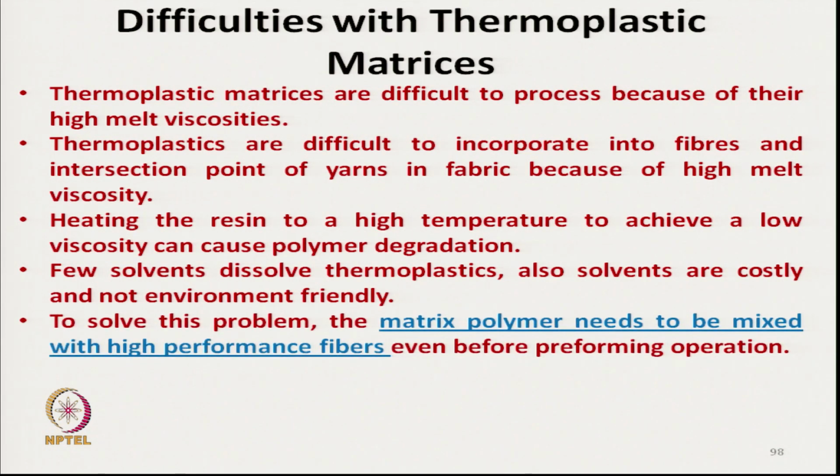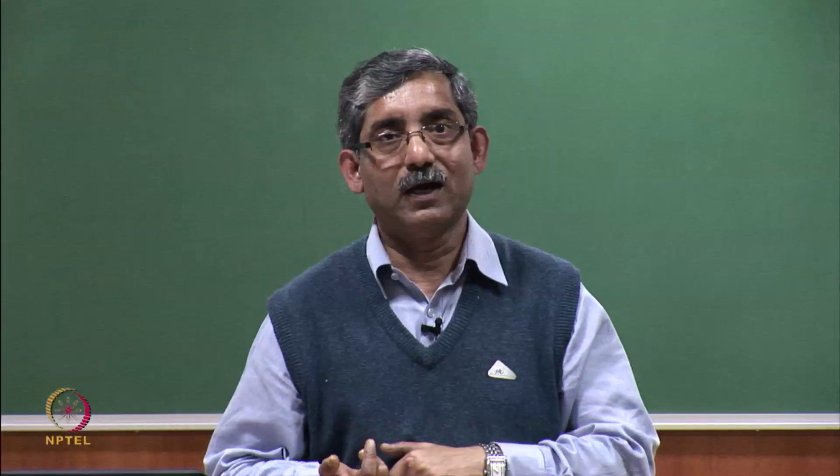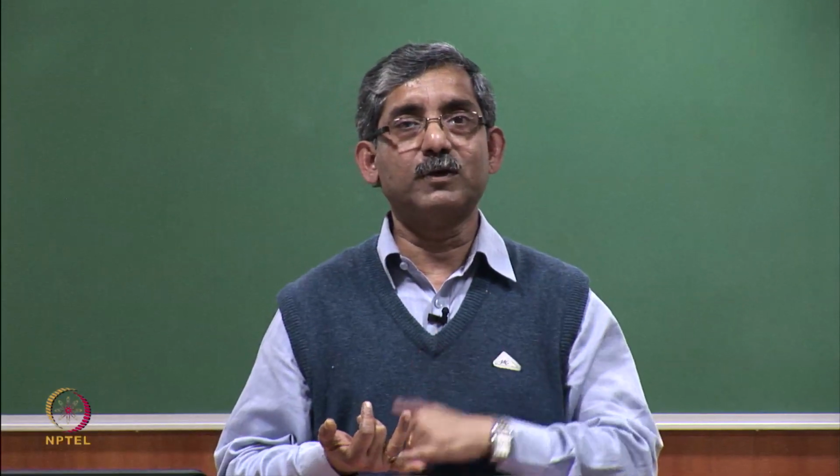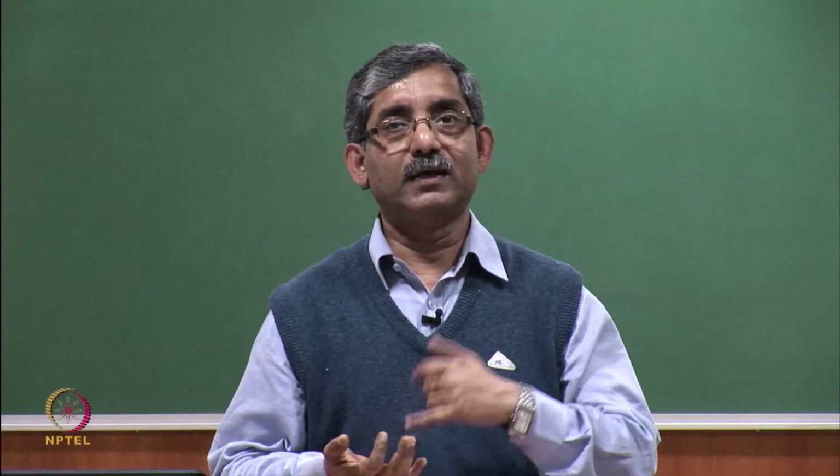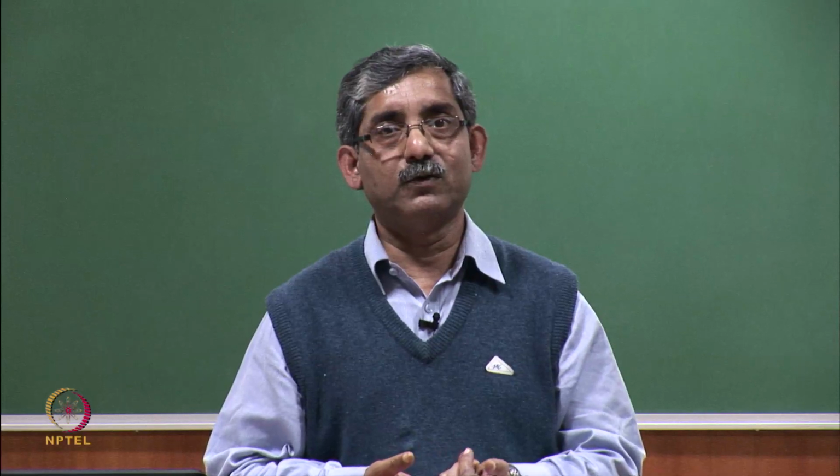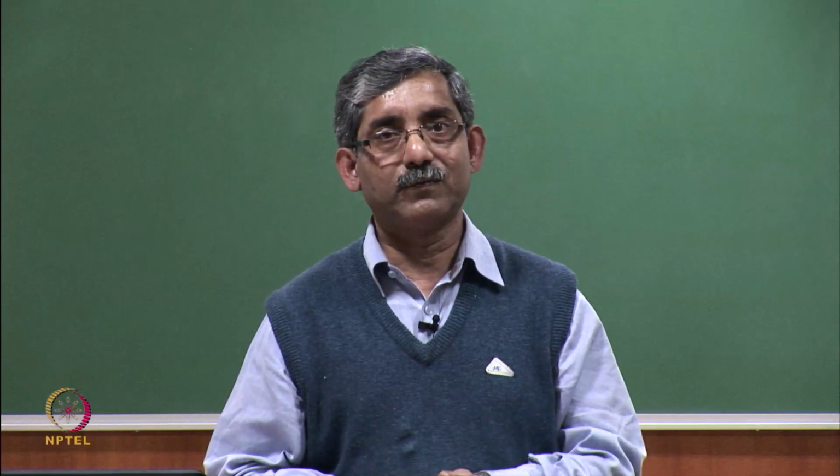So, what is the solution? The problem is high melt viscosity, and we cannot reduce the viscosity by increasing temperature due to degradation problem.